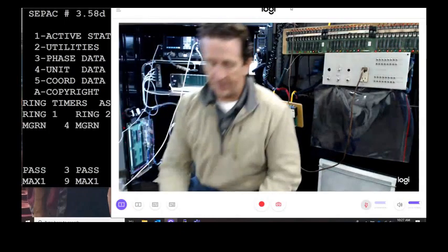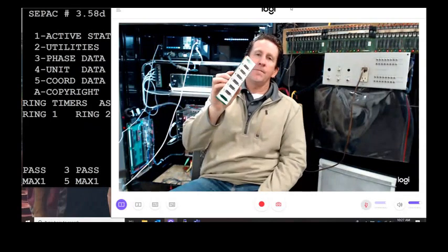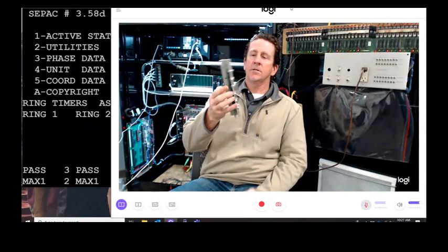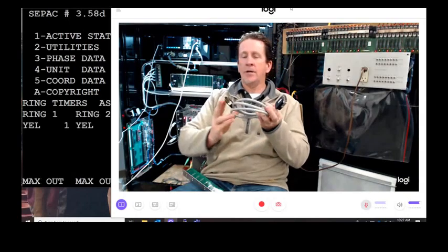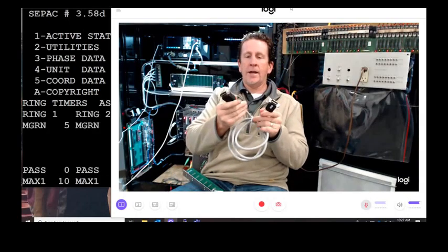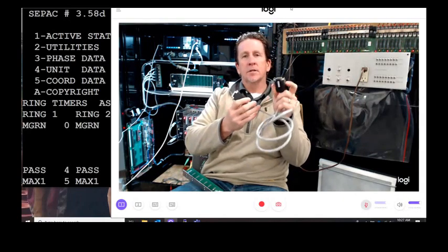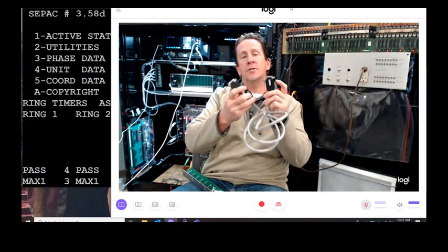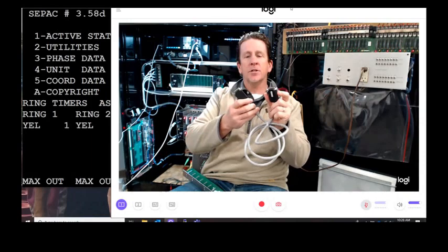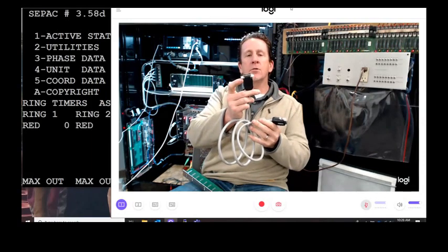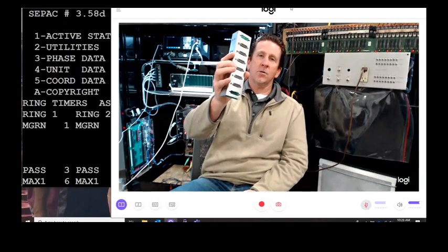We've gone over this before. So in a Siemens cabinet, we have the hub. This is what we call the hub assembly. So this mounts on the side panel. And then we have the BIU cable. You'll see one end has screws on it right here, and the other end has the clips. The clip end goes on your device, your controller, your MMU, your BIU. That's why we have the clips on there for security. The screw end goes into my hub assembly, which has female slots, so I can screw it in and secure it on there.